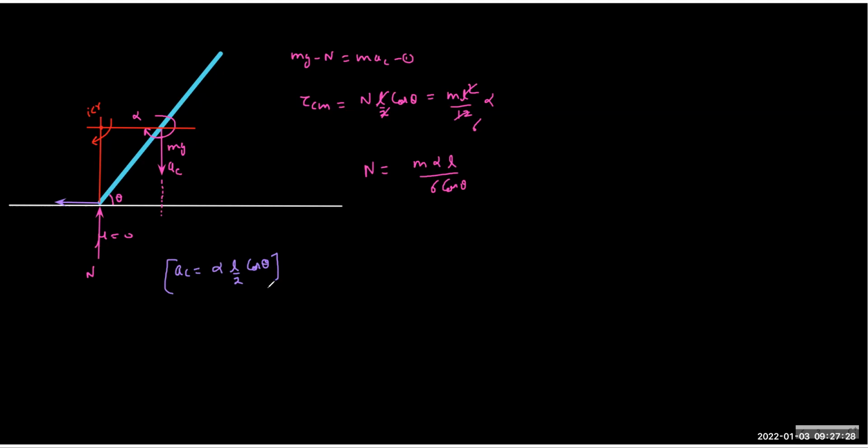And therefore you can solve this entire equation. So it's totally solvable. But there is another way you can also derive it. The kinematics part is easy because this is kinematics. It has nothing to do with the rotational dynamics. So the bottom is trying to go left. The bottom will have zero acceleration in the vertical direction. Correct. And the acceleration of the center of mass is a_c.